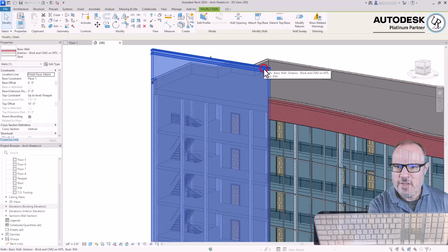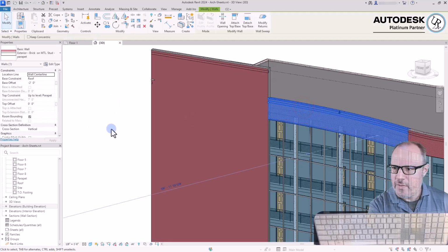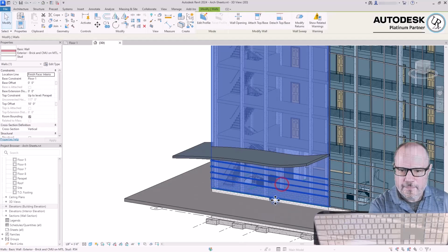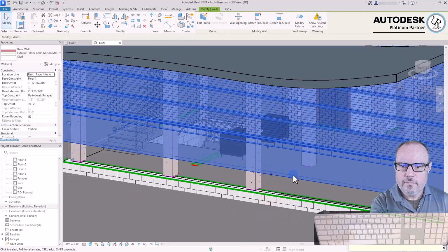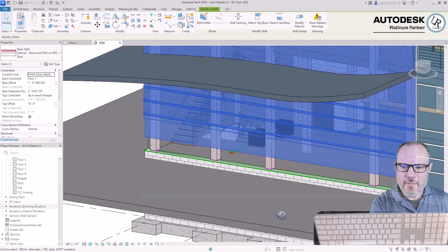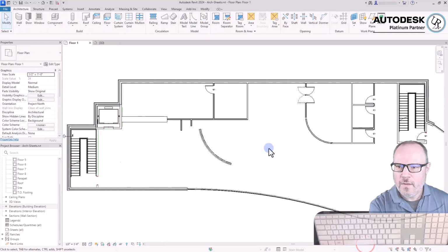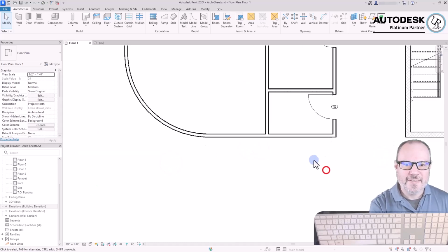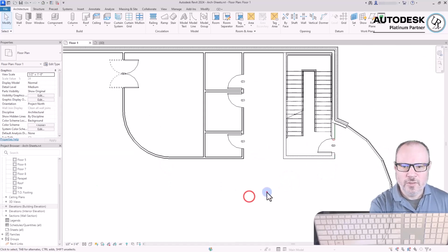You can completely adjust each individual wall type, one at a time, with those properties, from the base or the top. Raising the wall off the floor, or dropping it down below the floor. You will typically have more wall locations inside of an entire project than most other items because of all of the different wall facets, smaller segments of wall, and different wall conditions.